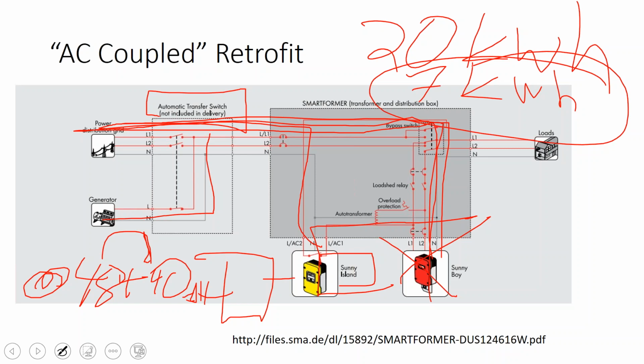And the customer is buying it not to make an economic payback on their battery, but to have more power security during a blackout. And then the question is, well, how much power security do you want? Because if you go with the 7 kilowatt hour battery bank, that's hardly, think about your microwave. Your microwave might use 2,000 watts, or a tankless water heater can get up to 20 kilowatts. So the Tesla Powerwall only has enough power in it to run a tankless water heater for about, I don't know, 20 minutes or so. That's not very much.